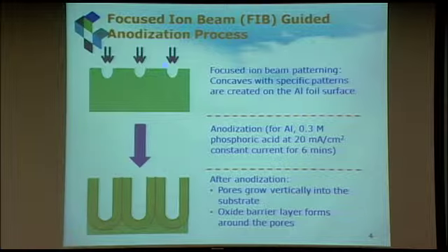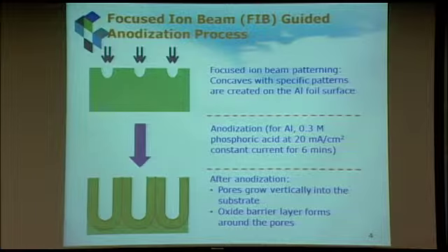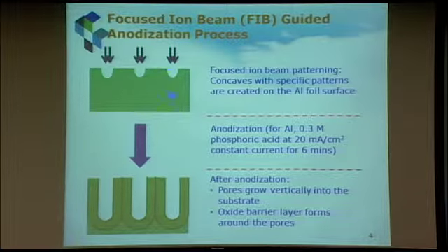If you say, why don't I just use focused ion beam? Focused ion beam is great. But the problem is this beam has this Gaussian distribution. You end up with these kind of tapered pores, and then you go very deep, because when it's really deep, you bombard your material off, and then it's going to fall back in. So there are quite some limitations on this.